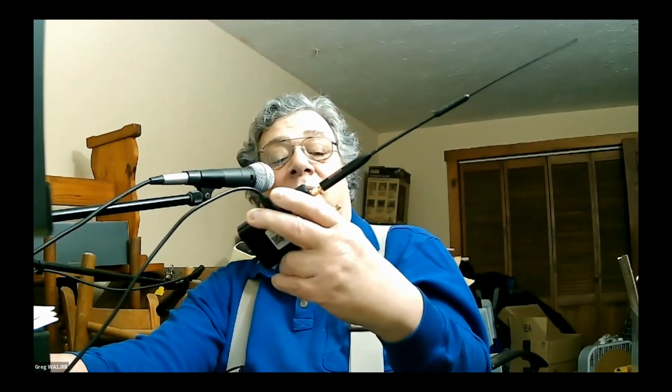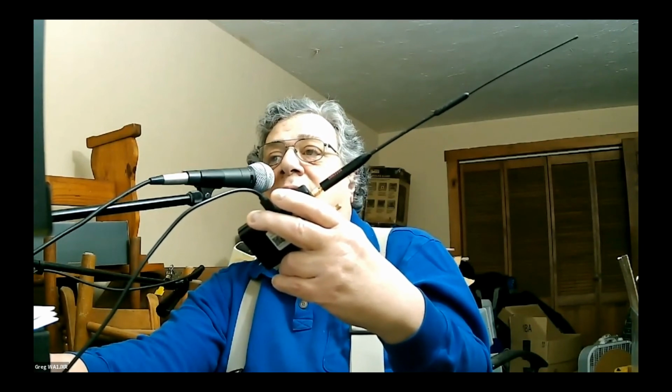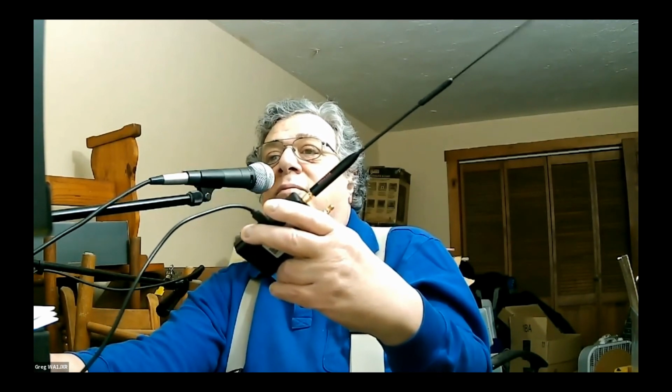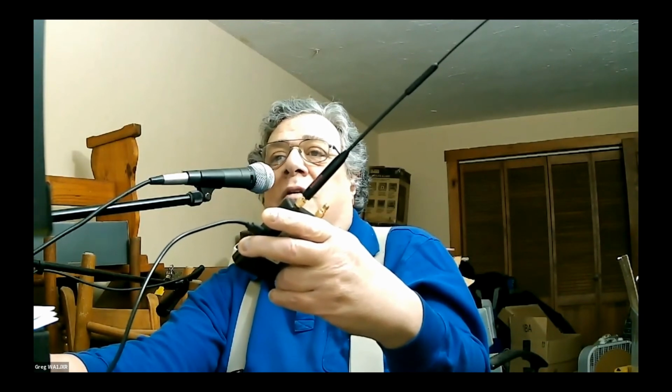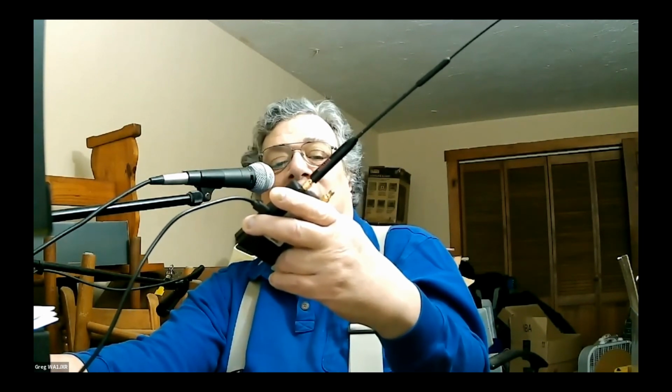I've set the Nano VNA up. I already calibrated it. I'm not going to bore you guys with watching me put short, open, load, and through on. I calibrated it for a start frequency of 100 megahertz and a stop frequency of 500 megahertz, because this is a 2 meter 440 antenna, so we want coverage in the 2 meter 150 meg range, and we want coverage to measure the antenna in the 450 megahertz range. So I set 100 to 500 megs as the start stop.